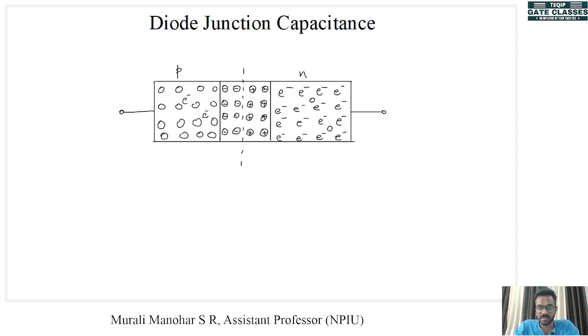So there is a charge separation. There are regions that act like electrodes, that is, the conducting plates. So that means this region will look like a capacitor. There is also this point that in the depletion region, electric charges do not move from one place to another. That means they will be producing an electric field there, right? So here charge is stored at the depletion region in the form of an electric field. So we can say that at the depletion region we have a capacitor, right?